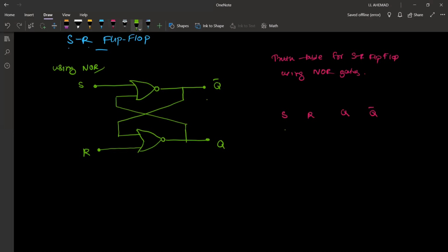When set and reset, you are not providing any. Now here only the sensor will be connected. Okay, in between we may use a NOT gate or whatever before this set. So when set is 0, we are not resetting. Reset is also 0. Let's say the output is 0, Q is 0 and Q bar is 1. If this is 0, this has to be 1, right?